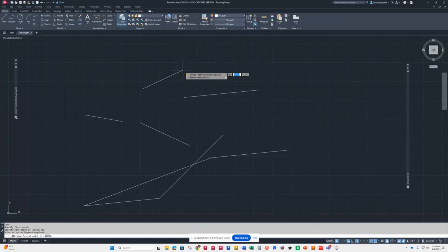All right. I didn't put in a point, so now it doesn't like me. So I'm going to do at 6, angle 80. Okay. So relative coordinates, X and Y. Don't care where I'm at. I know where I want to go to. X and Y from where I'm at.